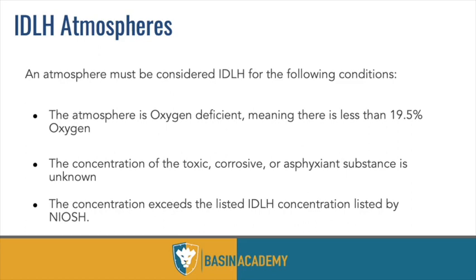So we'll send 2 guys. They're both fully masked up. They're both under air. One might have an air line. One might just have a 30-minute pack. We got a buddy system. We got a rope out. I mean, we're ready to rescue a guy in case something were to happen, right? We treat unknown wells or unknown situations as though they were fatal because you don't know.